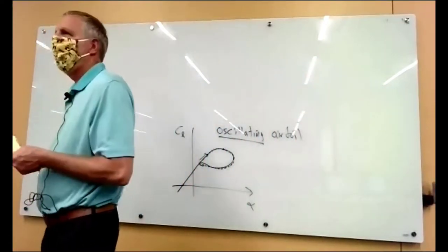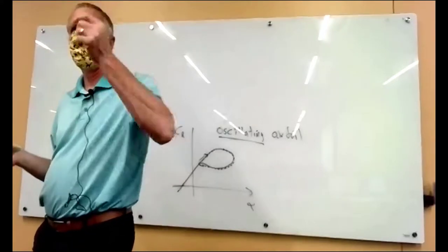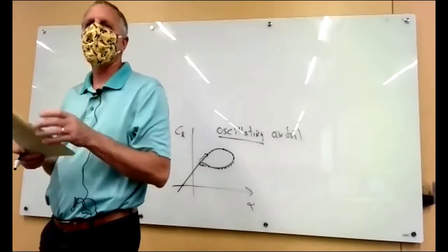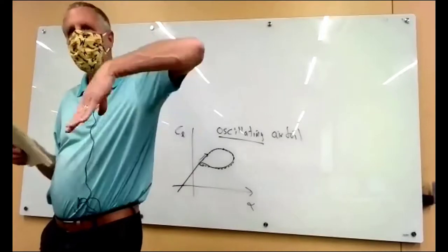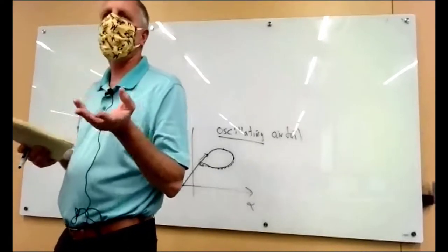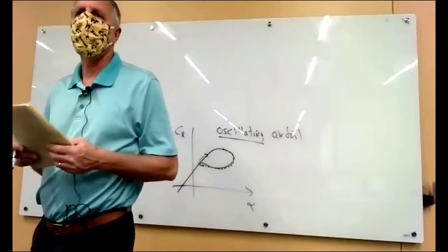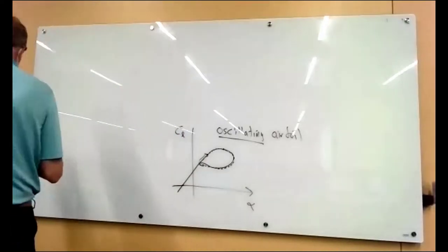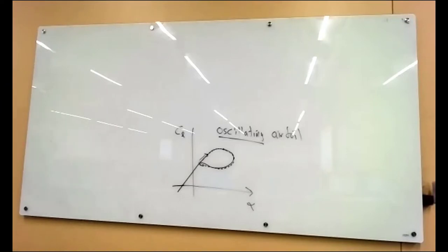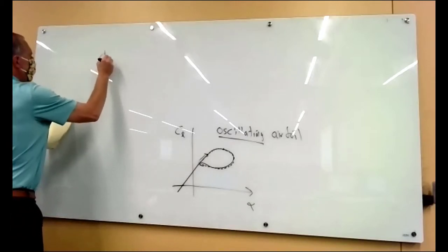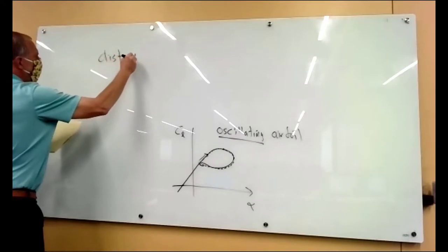So the idea is that the downwash comes from the trailing vortex. Any airfoil, if it's oscillating, it's pitching up and down. So if you have flutter, the wingtip is fluttering up and down in pitch, and so you get this behavior. So the idea is that the downwash takes a certain amount of time. It's developed on the wing. So if you change the angle of attack, it takes the distance from the wing to the tail for that effect to be felt by the tail. And so that's the key factor, the distance from the wing to the tail.